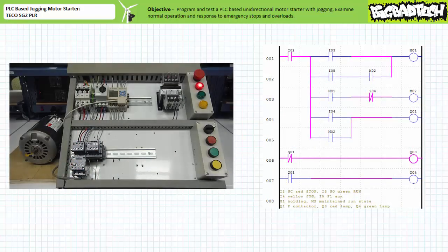When the program is downloaded to the target device and placed into operation, we can observe its behavior and simultaneously monitor the program using a live communications link. Note the two videos are synced up, however there's a noticeable lag in the monitoring utility. As can be expected, when the system is in the deactivated state, the F contactor coil is not energized, the F primary contacts are open, and the motor is off.